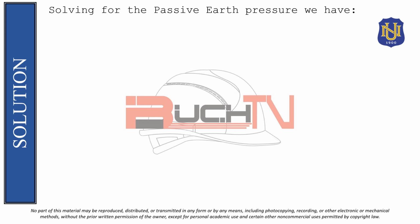So, after solving the passive earth coefficient, we will solve for the passive earth pressure coming from the equation P sub P is equal to gamma H K sub P. So, pure direct substitution, as long as we have memorized the formula and the procedures.